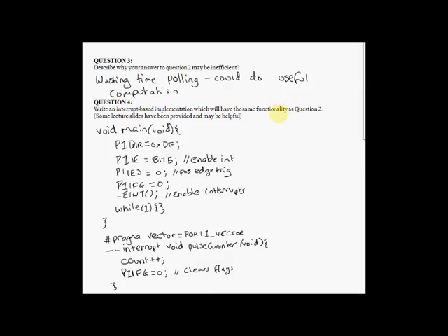The only other thing that we should mention is that we should have declared our counter to begin with, and the counter will be a global variable, so we'll declare it up here somewhere. And we should declare it because we're using it in our interrupts as a static volatile. So static volatile int counter.